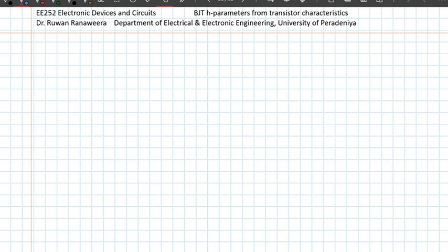It's a little bit more than just the diode characteristics, since it depends not just on IB alone, but also on VCE, whereas for a diode you don't have a VCE, right? So this is going to be a little bit different, but you will see that the difference introduced due to this additional variability is very small, so often we can neglect it.